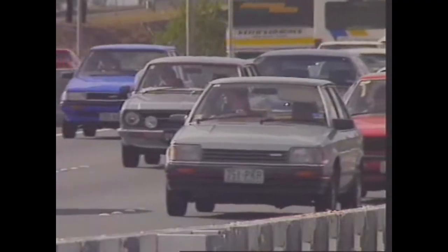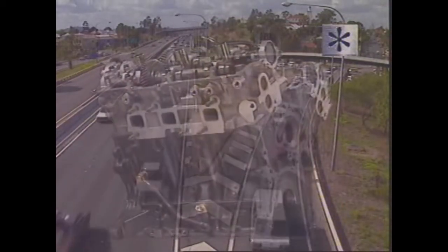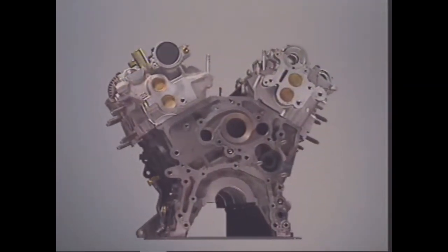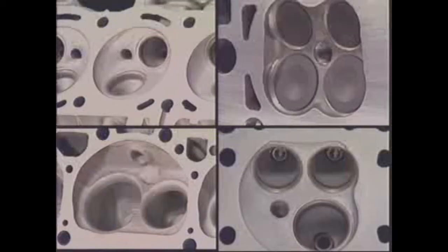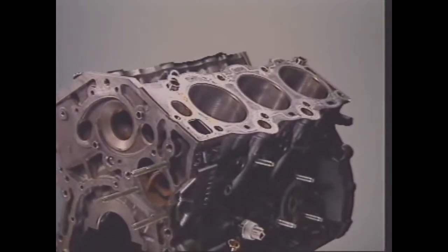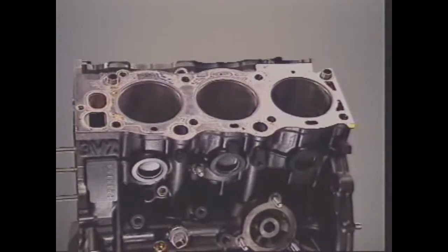Many vehicles still use cast iron, but some have aluminium alloy blocks. The main gain is a saving in weight. Aluminium alloys can be made as strong as cast iron, but they're lighter. This is also true for cylinder heads. Combustion chambers in the cylinder head come in many different designs. To help hold in the extreme heat and pressure of combustion, a seal is made between the block and cylinder head by a head gasket.